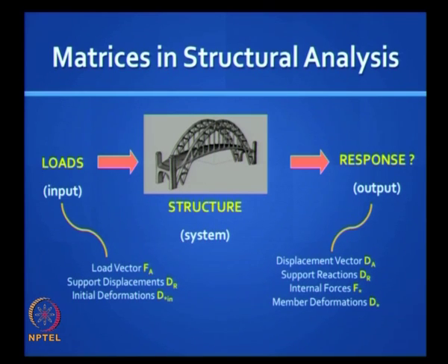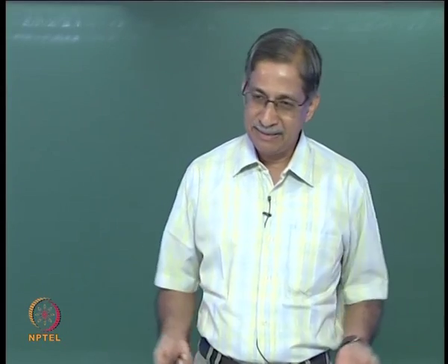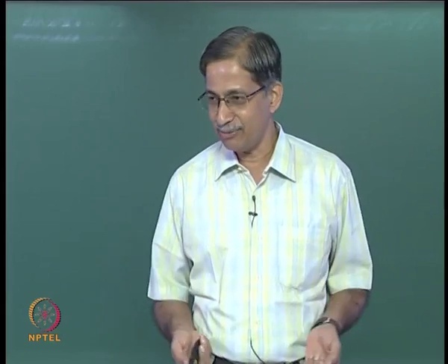So basically you have some unknown quantities and some known quantities in the displacement field and the force field, and you need to know certain laws which are hidden in the structure which enable transformations to take place. So basically we want to transform the loads to the responses, and this becomes relatively easy when you are dealing with a linear analysis, because it is a linear transformation.